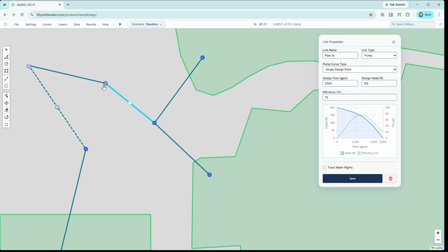Okay, so if we don't change anything about the operations, the way that the model works is it looks at ensuring that we stay far above the wilting point of the crop and below the field capacity, and just pump as needed to maintain that soil water depth over time. And it also looks at the pressure at the delivery point that is required for that.